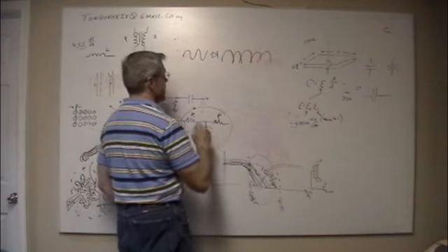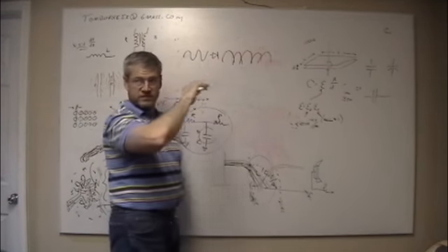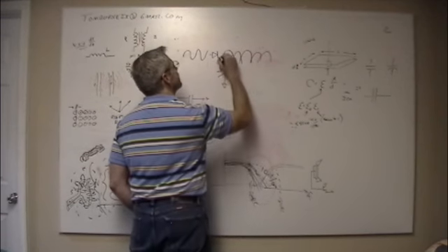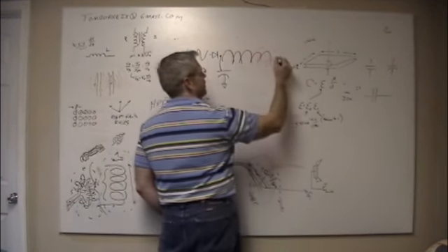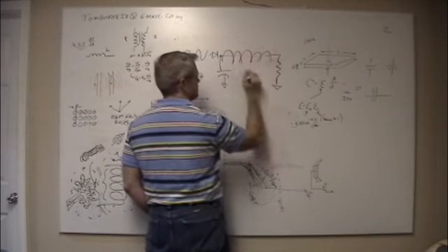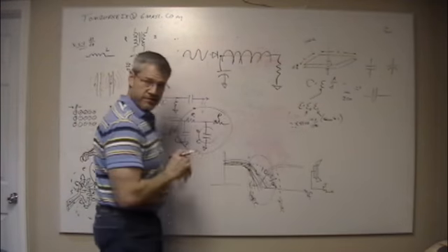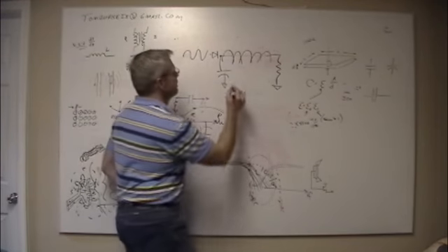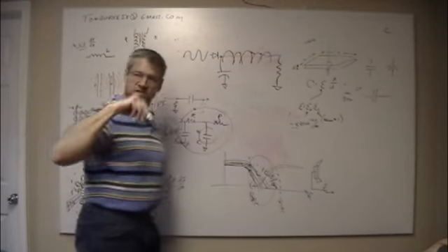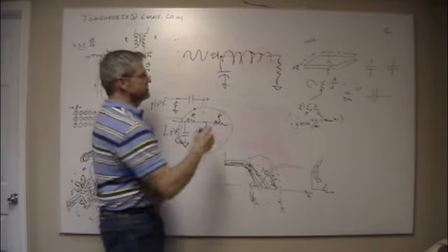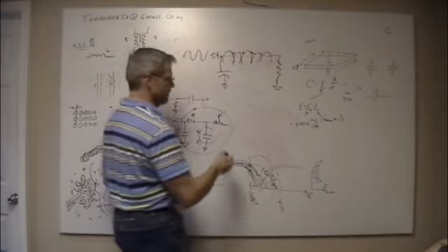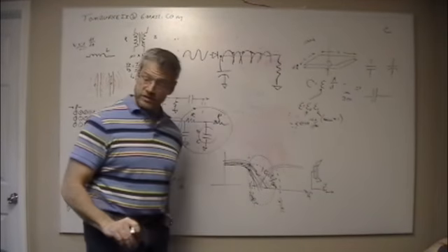You have a filter capacitor, and you kind of know what the resistance of your power supply and everything else is. So you choose this capacitor here, based on the load that you're going to see out here, so that what happens is, and this is exactly what happens when we showed it up here close, only we're talking higher power now, you basically get this. It fills in these gaps between the peaks of the sine waves. And so this is called your ripple current. And if you get that down suitably low, you won't hear it. What you're looking at is, do I have to draw tubes?